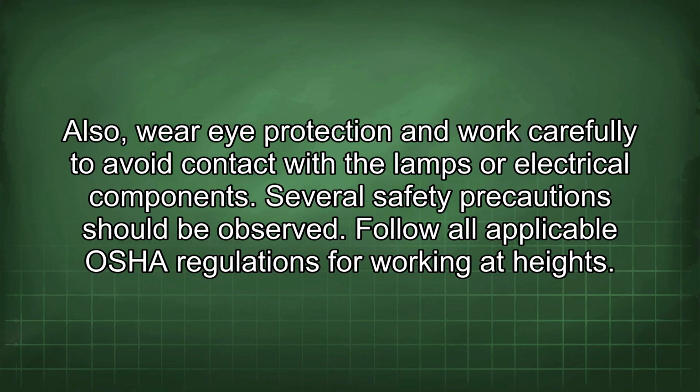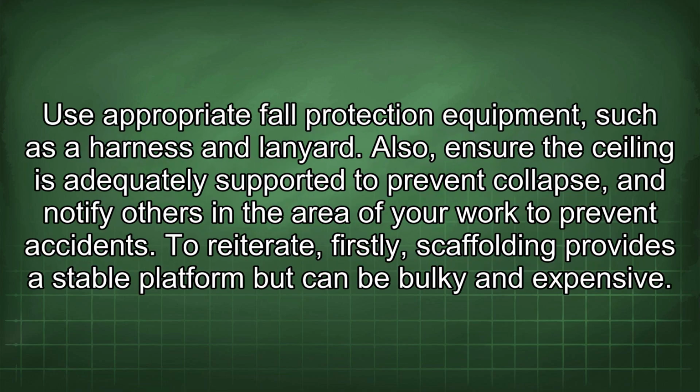Several safety precautions should be observed. Follow all applicable OSHA regulations for working at height. Use appropriate fall protection equipment, such as a harness and lanyard. Also, ensure the ceiling is adequately supported to prevent collapse, and notify others in the area of your work to prevent accidents.